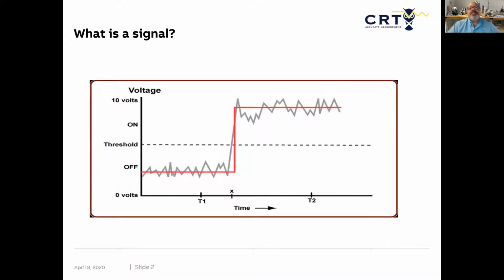So in doing this, we have a base voltage or a 0 volt condition that we have to look at. Now, flow computers, the FlowX specifically, the inputs are floating. So it means that I don't necessarily have to go to ground with them. I can just go to a reference voltage coming off a power supply, and that's going to be my 0 volts. Now, when we have more than one device connected, and I'm bringing a signal into the FlowX, I need to make sure that those power supplies are either bonded or I'm using an isolation relay so I can give myself a reference common.